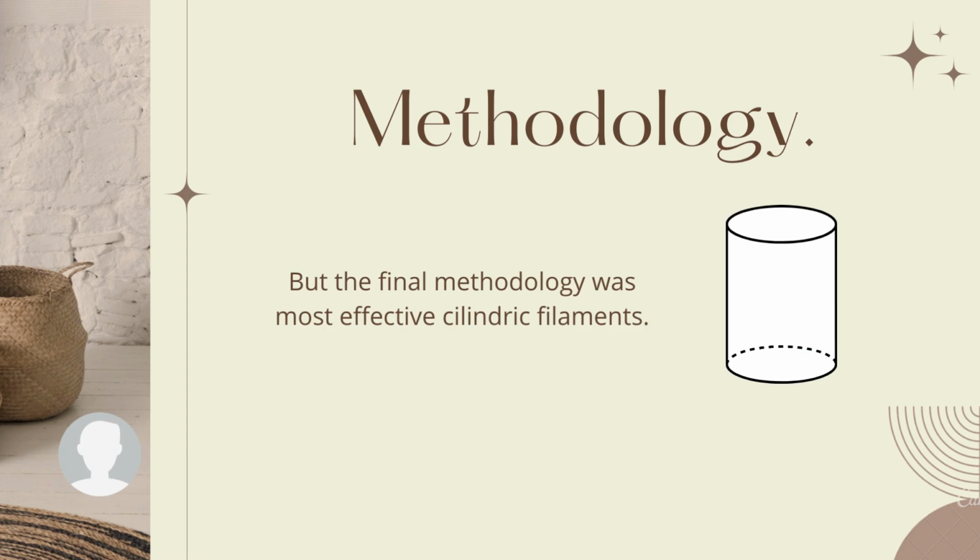The final methodology was most effective for cylindrical geometries due to the heat conduction over the z or height dimension, because the heat source was put at the lowest point of the filament and we measured the temperature at different points in the z direction of the filament.